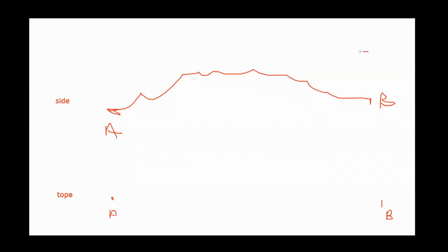You start taping in this direction. But if you look at the top view here, if this distance is, let's say, 1,500 feet, you can't get it from one tape. So what you need to do is break it down into segments of 100 feet, and so on. I'm drawing these lines on purpose not aligned together. This is AB, by the way.